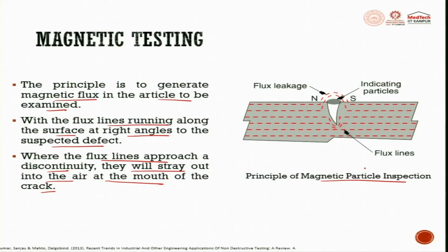In magnetic particle inspection, the flux leakage only detects the anomalies in the normal flux patterns. So these are discontinuities. In ferrous material, this is quite applicable. This is used for piping, tubing inspection, then tank floor inspection, and other applications are also there.